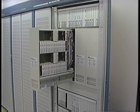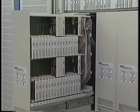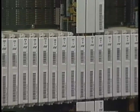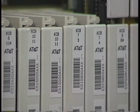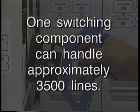The switching component consists of several units. The line card unit, or LCU, interfaces customer lines and the digital system. A customer's 2-wire or 4-wire line is connected to one line card. There is a line card assigned to every customer line connected to the switching component. One switching component can handle approximately 3,500 lines.